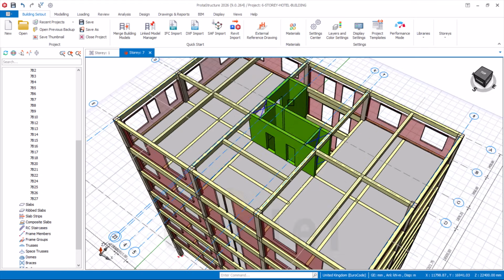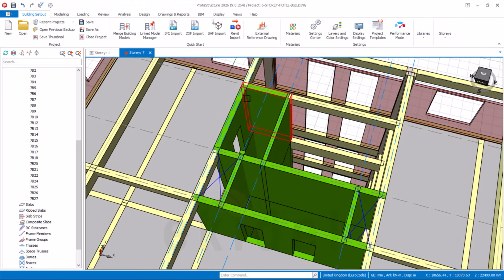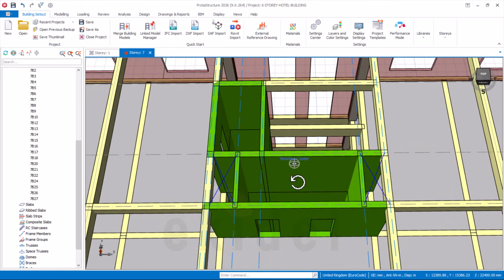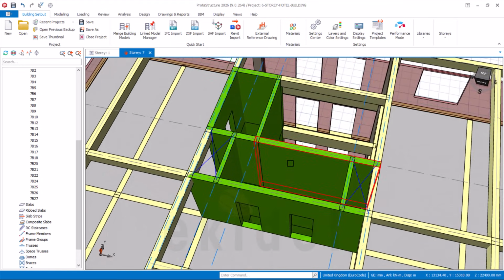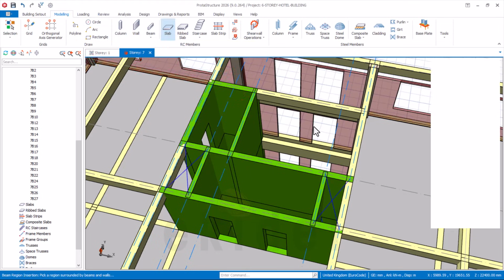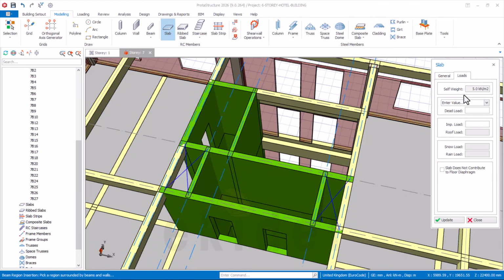Now know that this is the roof level, and on it this lift area is going to have a slab that the lift hook or pulley will be anchored to. So I'll click on my slab here, and make sure that the slab depth at the rooftop holding the pulley is at minimum 200. Then come here on the load, depending on the lift.